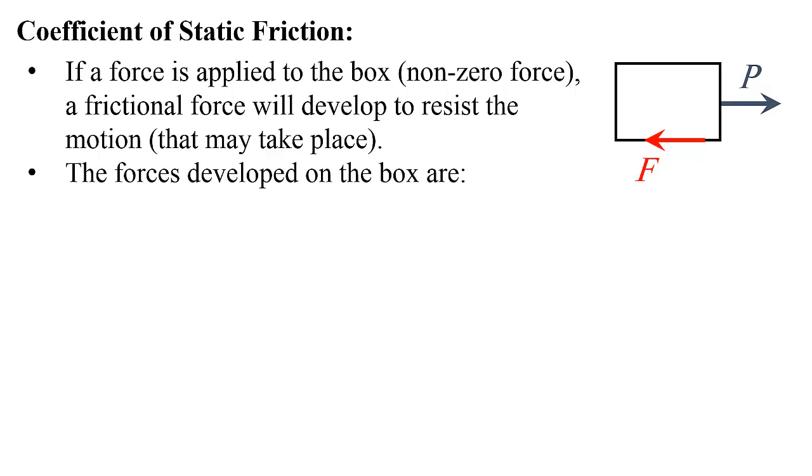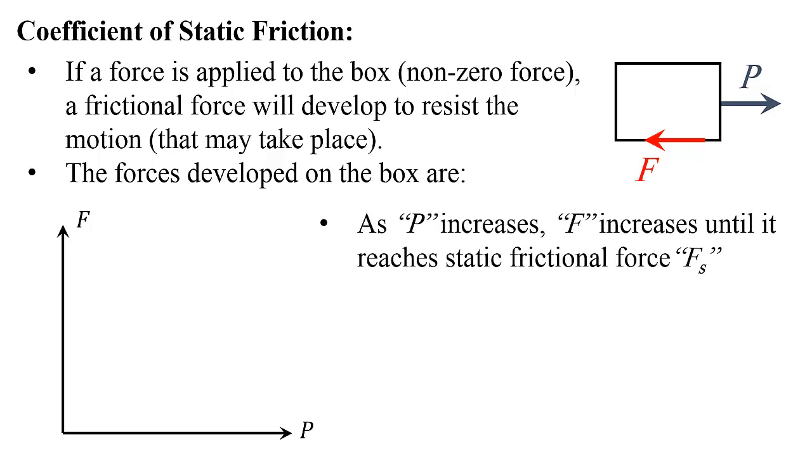The forces developed in the box are... So let's take a look at the forces graphically. Let's assume we have a plot. On the x-axis we have P, on the y-axis we have F. And now I'm going to increase P going from 0 all the way up. If I increase P, F increases until it reaches a static frictional force called Fs.